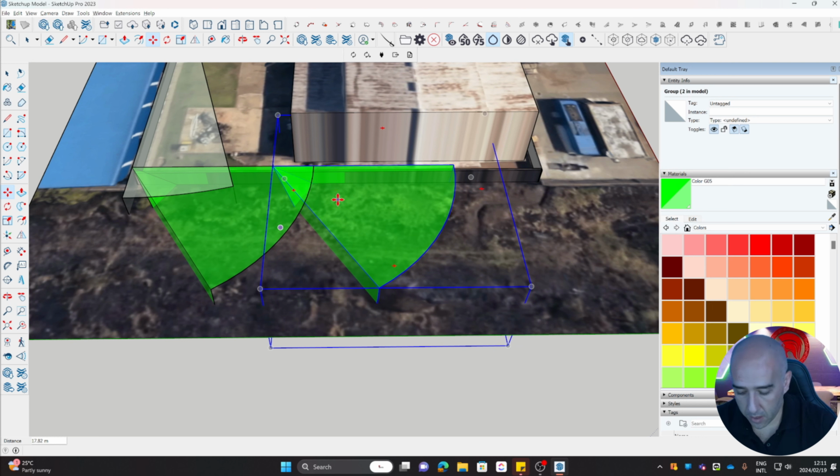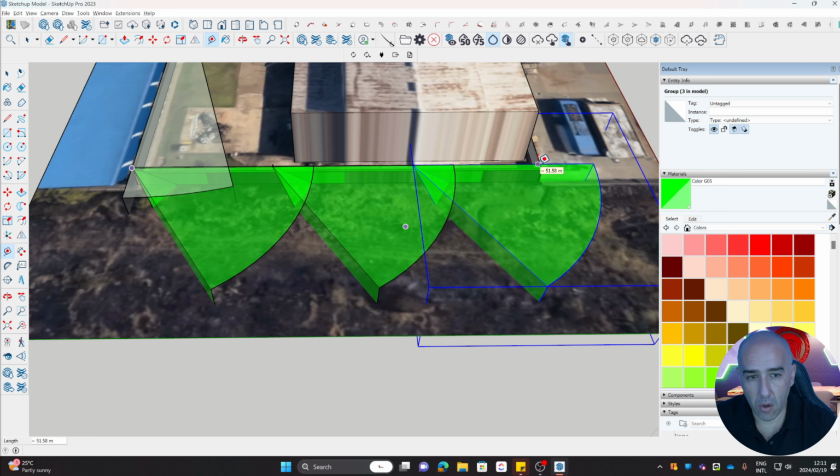And there's the back covered. Right now, I'm seeing that I don't think I should have 3 color view cameras in the back. I should actually put another thermal camera. But let's just look at how long this side is again. It's 52. Okay, and then the analytics of the thermals is going to go to 48. If I had to put another thermal in the back here, I would have to put a color view probably on the building to cover the blind spot.